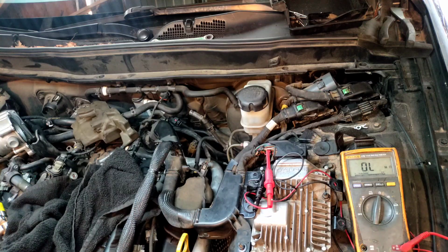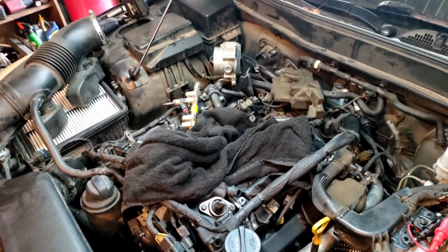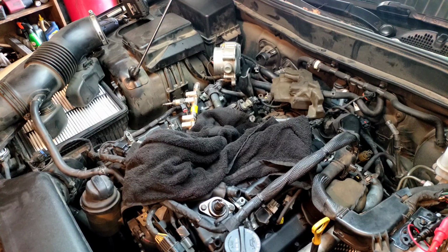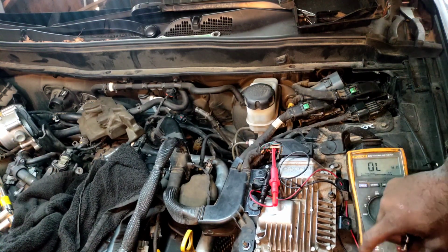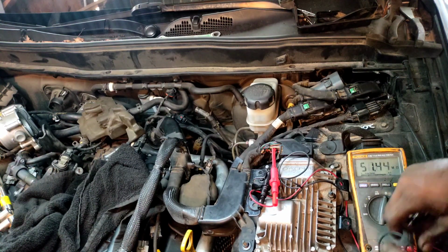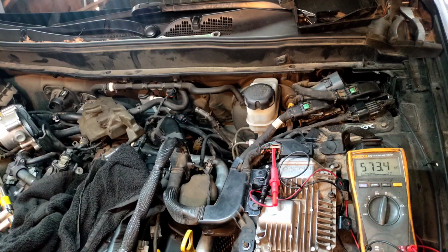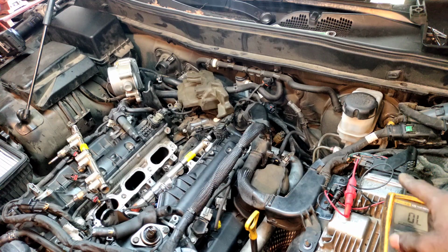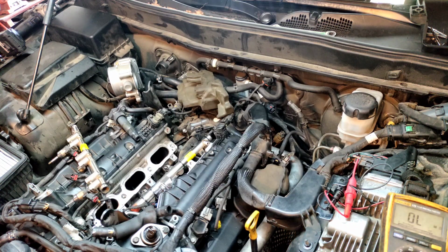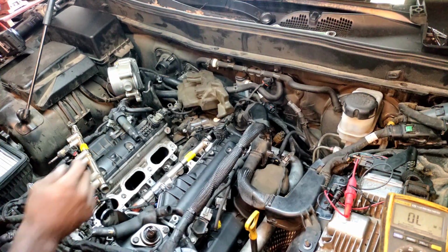What I'm gonna do, I need to get this installed because I got a lot of other things, and just recording is gonna take up a lot of time. Well, let me do one more thing. You gotta take in consideration when you have additional wires going to alter resistance value also. So I'm gonna plug this in, hook up the fuel injector from the main connector at the injector driver box. I do have it separated.